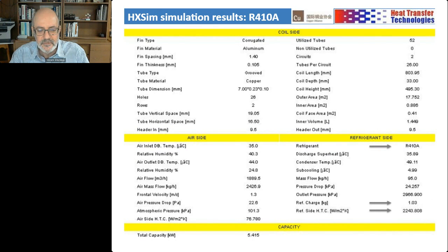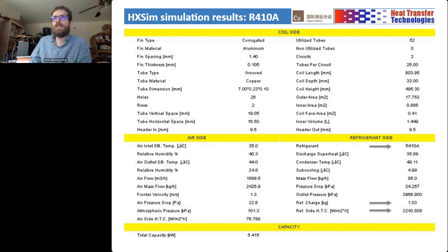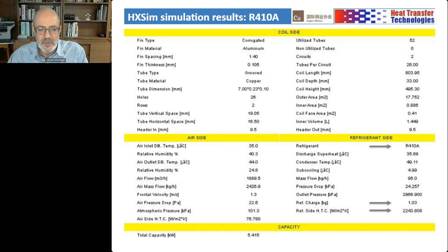Great, thanks, Yoram. Chris Mellon asks, any thoughts about refrigerant liquid overfeed similar to ammonia industrial refrigeration to increase wetting surface efficiency? Well, generally, what you want is 100% liquid going into an evaporator to maximize it. And there are liquid vapor separators that you can add to a circuit to get close to that. Of course, you're starting to get separation even in the manifold, and it's never 100%.